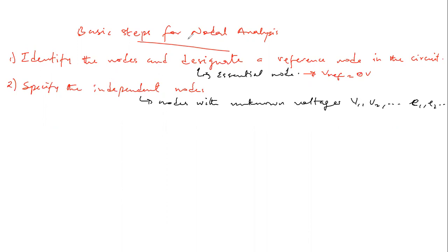And then the third point here to note afterwards is to assign current directions to all the branches in the circuit.